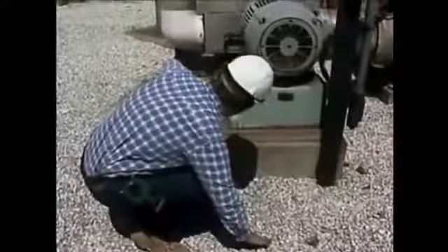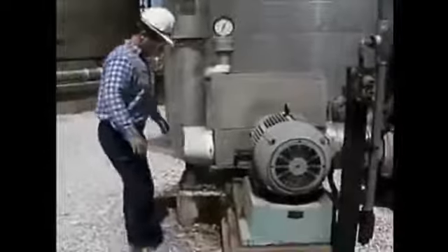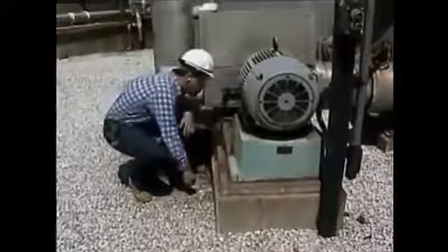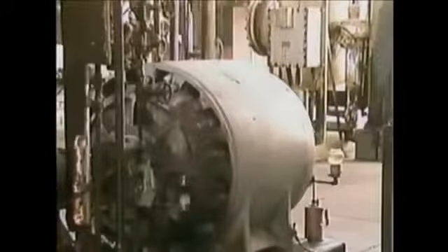There are some motors that use sealed bearings that do not have to be relubricated for the life of the motor. Other motors rely on a lubrication system to supply the bearings with grease or oil. If the motor uses a lubrication system, it's important to know how much oil or grease a motor is using. If the motor seems to be using an excessive amount of lubricant, check for leaks.